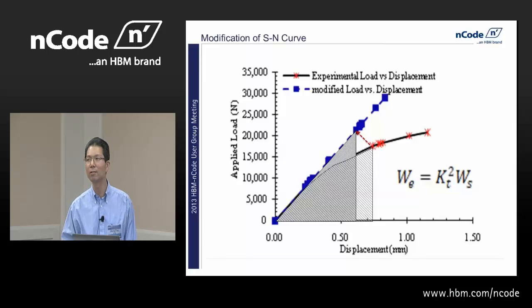Whether that 1,000 cycle loading is right in the FEA representation, that is the question. What we believe is that it is probably not right, because this already has plastic behavior in it, which cannot be captured in the linear elastic FEA. So instead of using the same amount of load, we have to move it here.